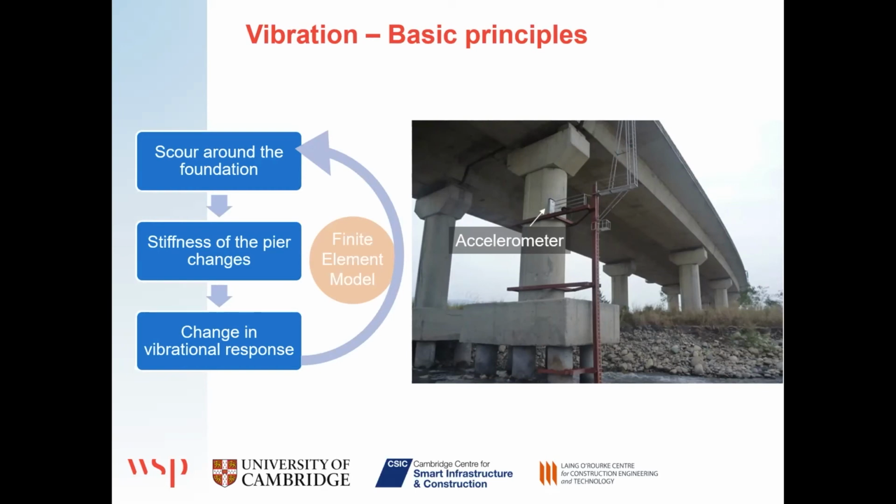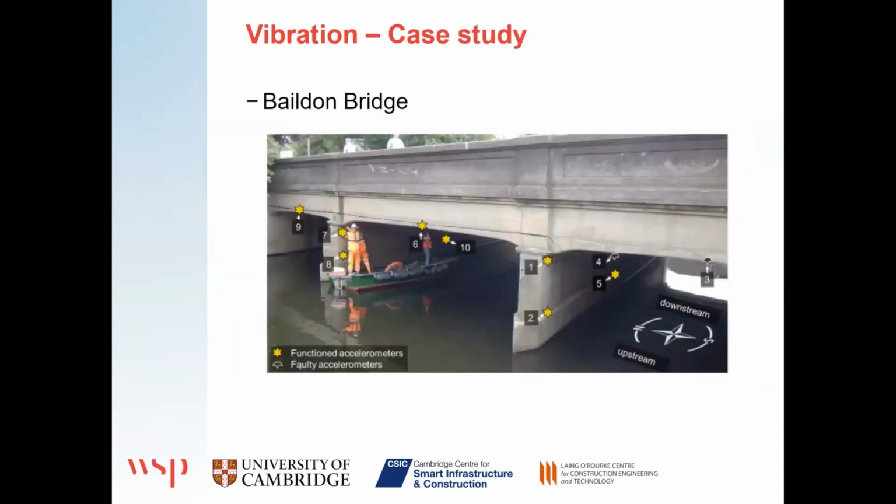And although the natural frequencies are predicted to change, work that Kaysen was looking at through his PhD found that the effect's really quite small compared to the uncertainty in your measurement, but changes in other properties like the mode shape of vibration of the columns and the power spectral density related to that are much, much more significant.